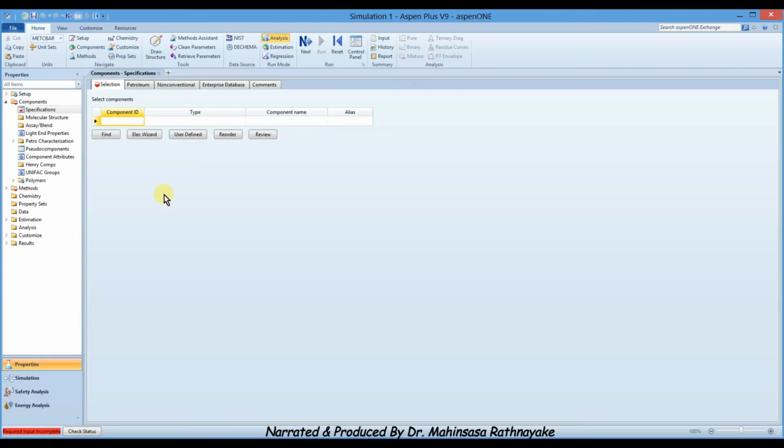Enter the components in our system. Those are water and calcium hydroxide. We can do this simulation in two ways, considering calcium hydroxide totally dissolves in water to be a complete aqueous solution. And the other way is calcium hydroxide remains as solid slurry within water. According to these two bases, the density of the solution used for calculations will be different.